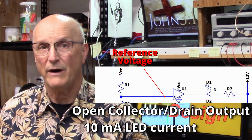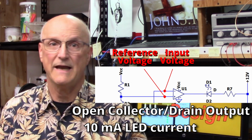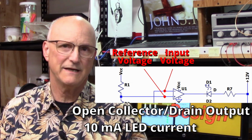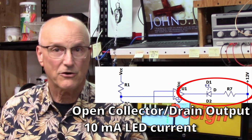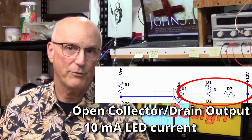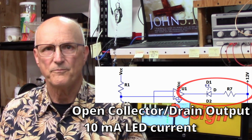By putting the reference voltage on the positive input of the comparator and the input voltage on the negative input, the output of the comparator will go low when the input voltage exceeds the reference voltage. With the LED and its current limiting resistor residing between the plus 12 volt input voltage and the output pin of the comparator, the LED will illuminate when the comparator's output is pulled low.